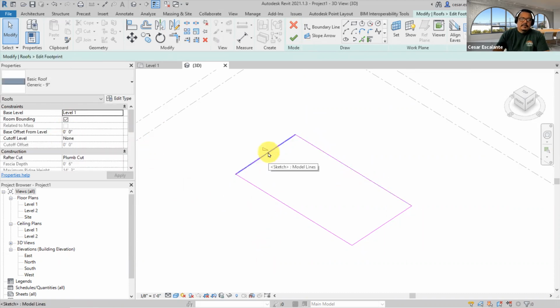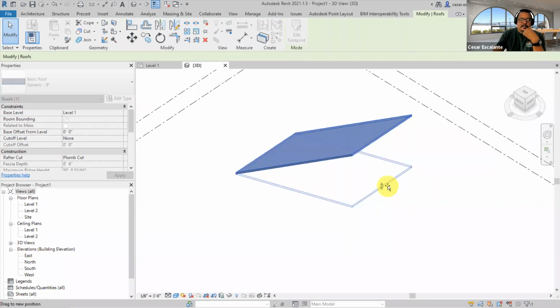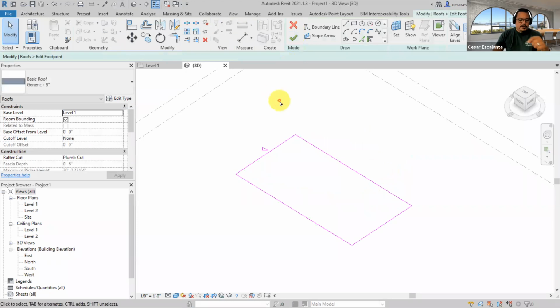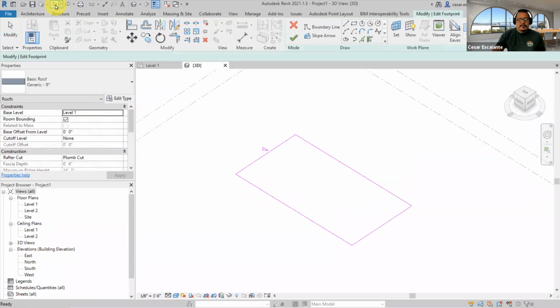This is a slope receiving edge, and so my roof is going to slope in this direction. So you hit the green checkbox, and you can change the slope using the handle. I'm going to undo and take me back to my 4-slope roof.